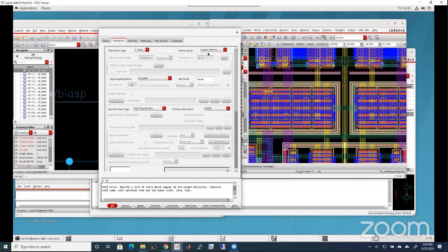So please all of you write down capacitance. There are three flavors of extraction: coupled, decoupled, and decoupled to substrate. Okay. Next thing, after that, there is RC. RC means it will break a wire. This wire will be broken into smaller resistor capacitors like a pi section. It will break it up and extract the netlist. All the wires will be broken down into smaller resistors and capacitors.